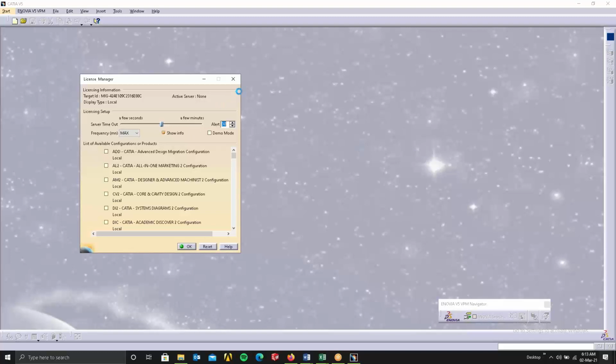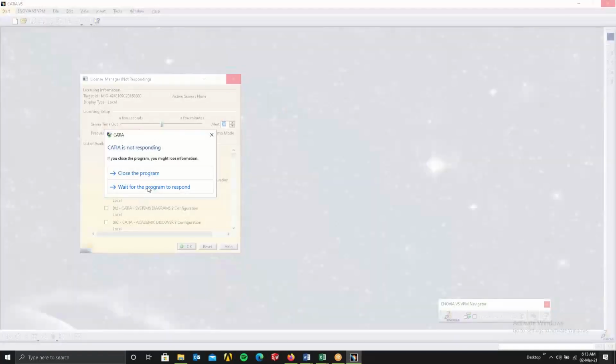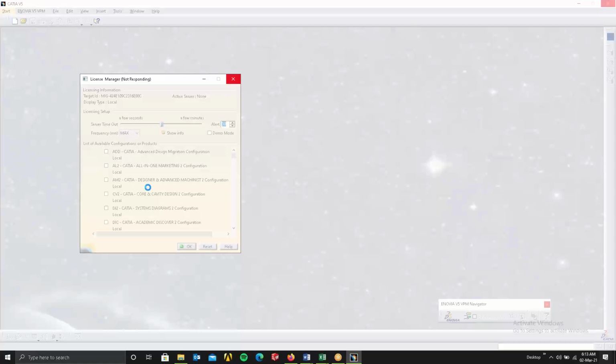And there's isometric, dimetric, trimetric, and orthographic. Very good. In isometric, we know that the object is oriented such that all the angles are equal. The alpha, beta, and gamma angles are equal. And in dimetric, only two of the angles are equal.